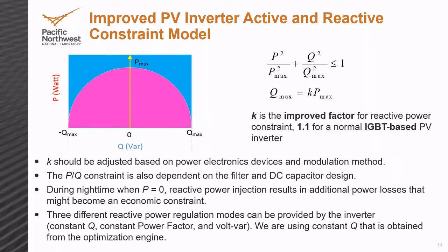I want to also, in the next slide, talk a little bit about smart inverter capability, which was also part of this work. So a smart inverter, a 4-quadrant smart inverter. This is the relation between real power, the y-axis here, and reactive power, the x-axis here.